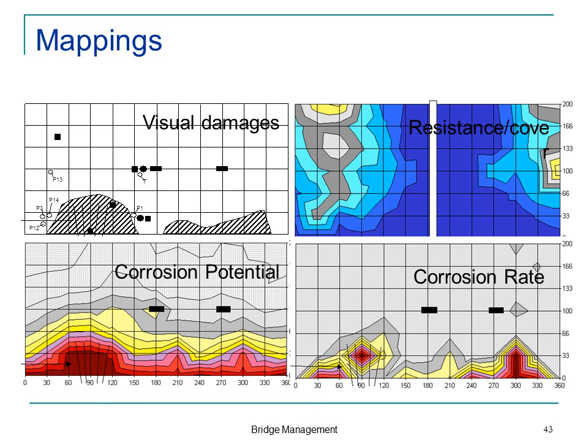And by doing that, we can combine what we see with our own eyes. And yes, someone back here, we can map the corrosion potential. That would be down here. There's probably a higher risk of corrosion. We could make a mapping of the corrosion rate, and we would say, here, here, and here, there seems to be a lot of corrosion going on. Ideally, we could use this for a prediction of how fast it's going to develop.